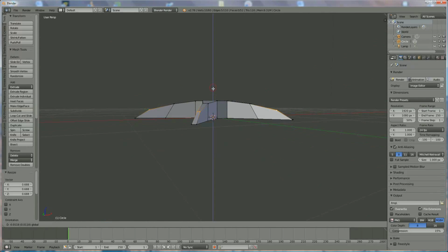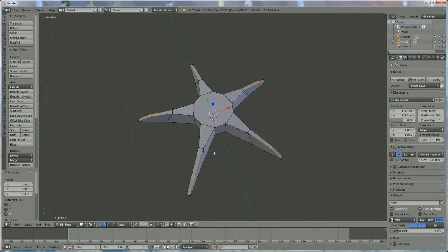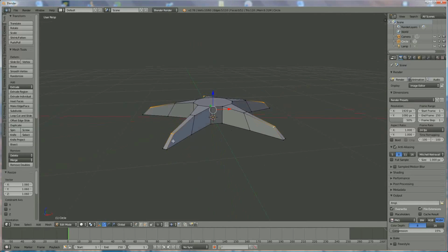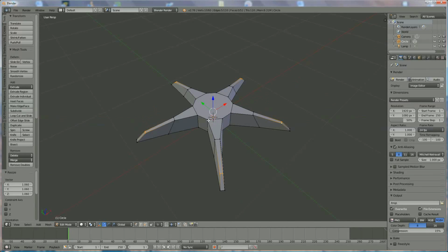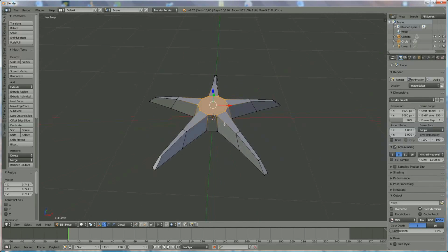I think it's probably better to look. And I probably had too much thinness to the center, so I put them a little more outside. Going to median point and S to make them a little larger like that, so we get a more pointy look backwards. Now we're going to select these. Same, Shift, hold down. And we're going to select in here the median point. Okay, we press S and we shrink it to that. Now, this is similar to the other one.